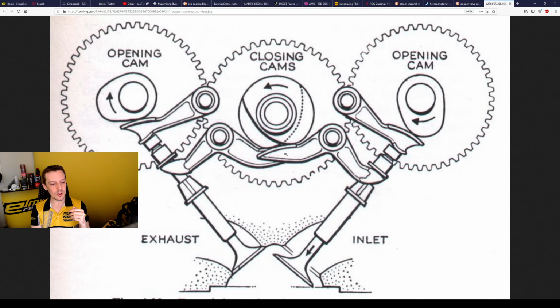So when you're pressing down really hard on this center lobe here, this L-shaped part starts to bend over, and then when you reduce the ramp rate, it will start flexing back, and then you can run into a problem where the parts start contacting each other.